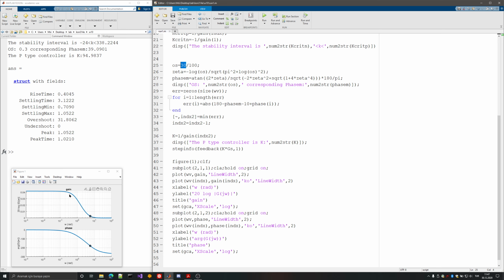So the algorithm is as follows. If you have the model, go ahead and use this model and the time domain approach. If you don't have the model, if you have an idea about the model or a Bode plot, then maybe opting for the frequency methods will be a better idea. So they're complementing each other, basically. So in the laboratory sessions or in homeworks, that's not the case.